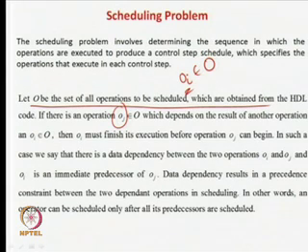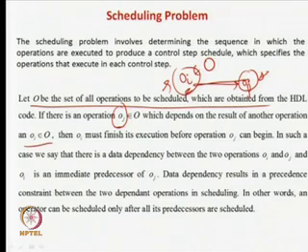But one thing you should be very careful about is if there is an operation Oj which depends on the result of Oi. It may happen that the output of Oi is controlling the output of Oj. In this case you should be very sure that Oi has already been scheduled before Oj is scheduled. Why? Because the output of Oj depends on the output of Oi. So Oi has to be computed first, then you can compute Oj. It is obvious that you have to give an earlier time step to Oi compared to Oj.